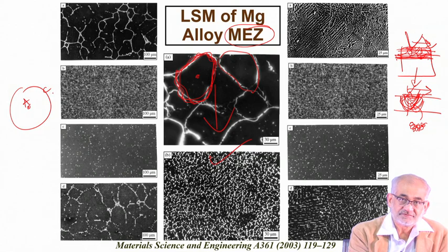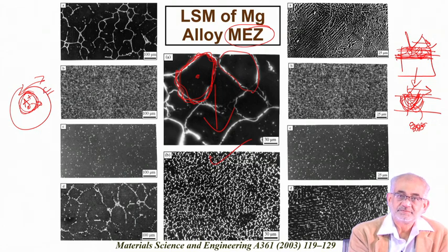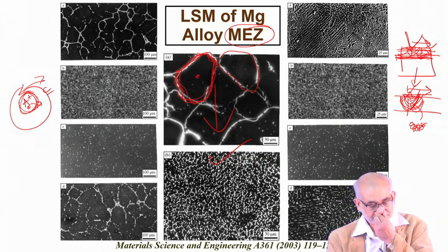As a result, there will be easy oxidation of this core, and because of this oxidation possibility, you'll create a galvanic cell between these two regions of the microstructure, and there will be easy corrosion happening. There will be dissolution of cations from the core, and the material will undergo heavy degradation.